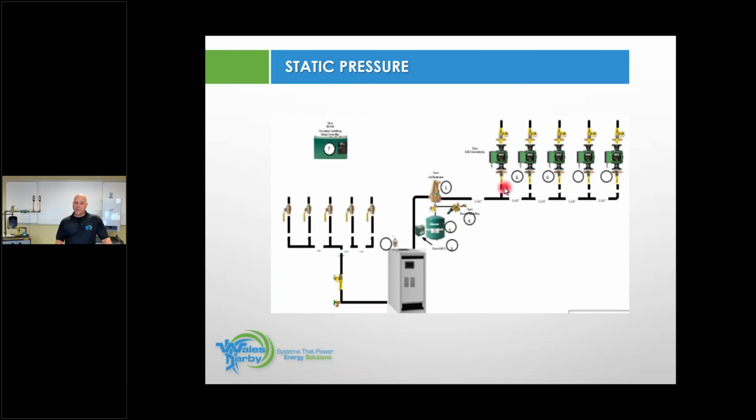So the backside will stay at normal pressure. The positive side will increase, usually 4 to 5 psi, and that will go up and around, overcome the head resistance of that heat circuit, back into the boiler to be reheated, and back out to make its journey again. So with all those parts and pieces right here in this area, they're all working as a system with the boiler and with the circulator and its location. You may have heard the term out there, Dan Holohan has always had the term, pumping away. You're pumping away from that expansion tank, you're pumping away from that boiler.